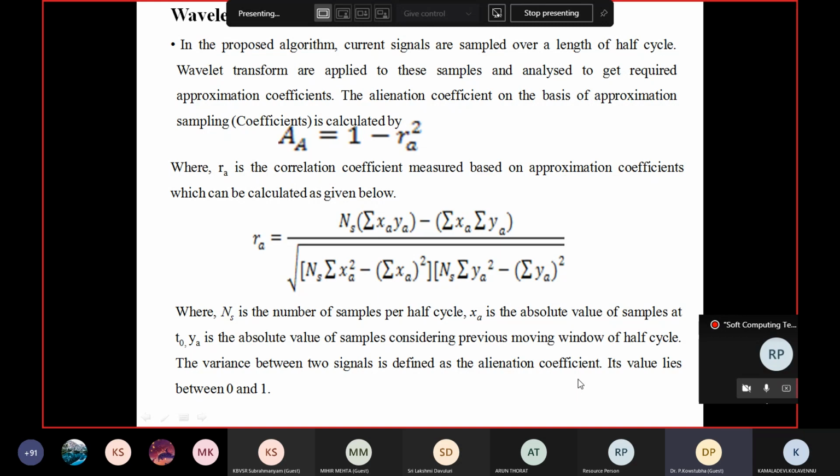That means after running the simulation diagram, simulating faults, either for an unusual condition or any disturbance, whatever it may be, islanding condition or fault condition. The islanding condition is simulated by opening the circuit breaker at the point of common coupling. Like that, faults are simulated at the location of the DGs in the transmission line. After completing the simulation, we can get current signals.